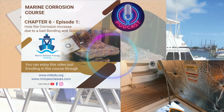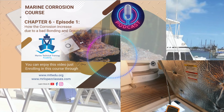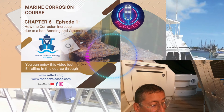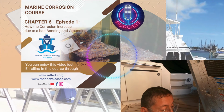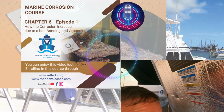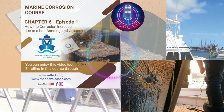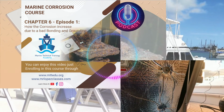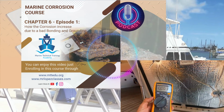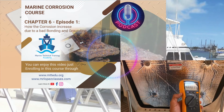Once again, it doesn't matter if it's for electronics or for AC or for DC, all the negative bus bars should be properly installed, properly connected. The cable should be professionally crimped with a heat shrink, properly isolated. This is the function of the negative bus bars in DC panels and ground bus bars in AC panels. Remember, all of them converge into the bonding conductor, and the bonding conductor finishes into the sink.